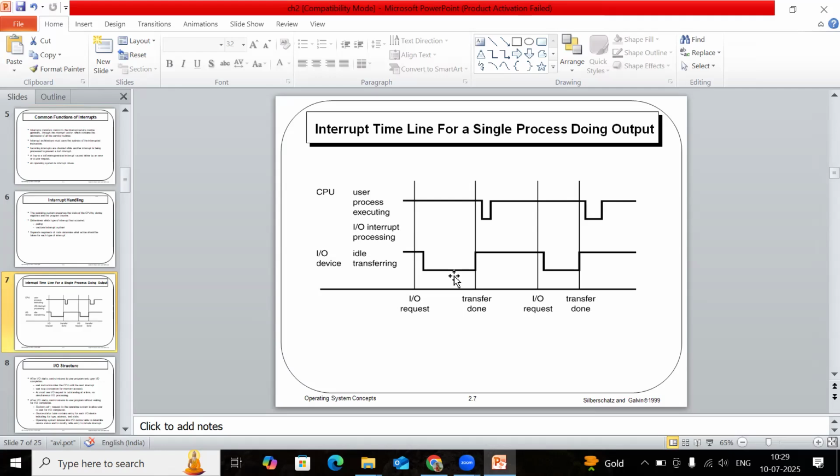When the CPU is interrupted, it transfers execution to a fixed location, which contains the starting address where the service routine for the interrupt is located. Every device request uses a fixed location in the interrupt vector.